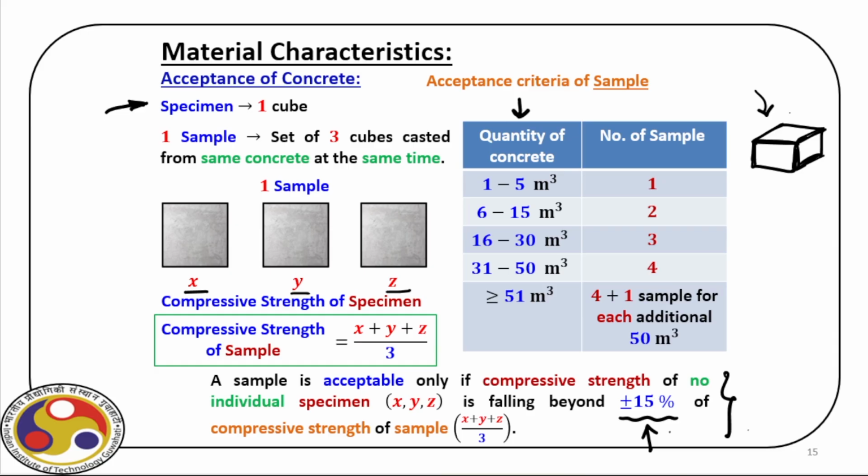Otherwise, if it is well prepared and well cured, then the standard option is we have to test these cubes, and then we have to find out the fck value, as we earlier discussed, that we have to have 5% area on the left hand side of this value, and we have already discussed how to find out that.